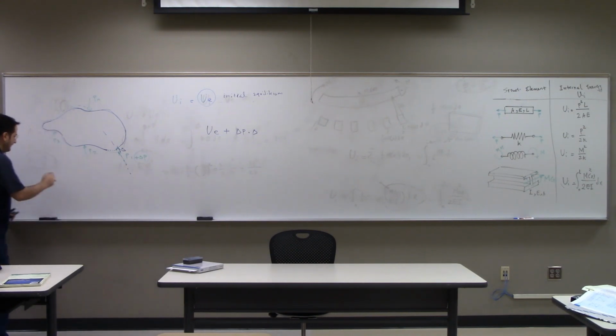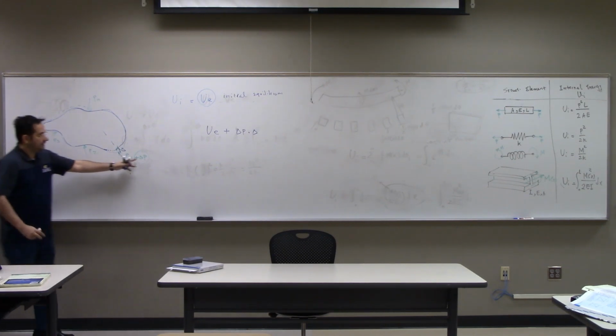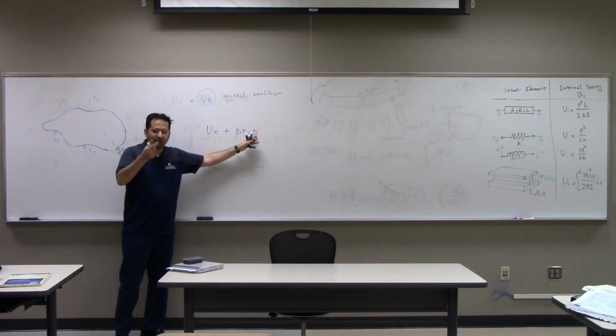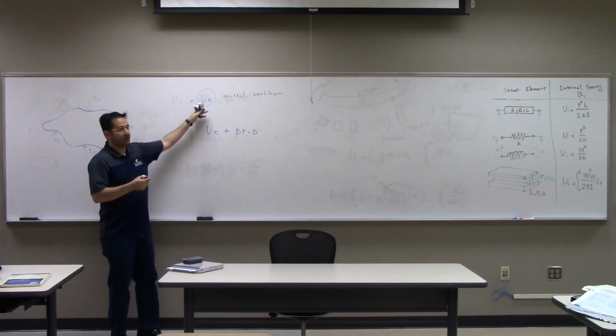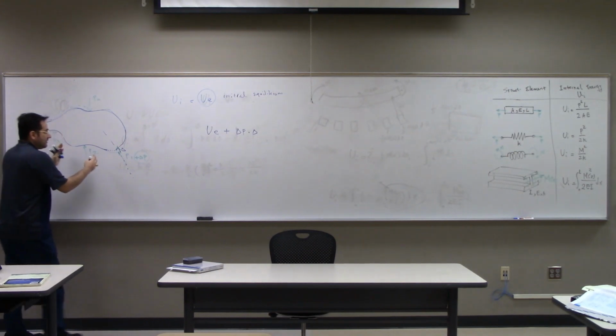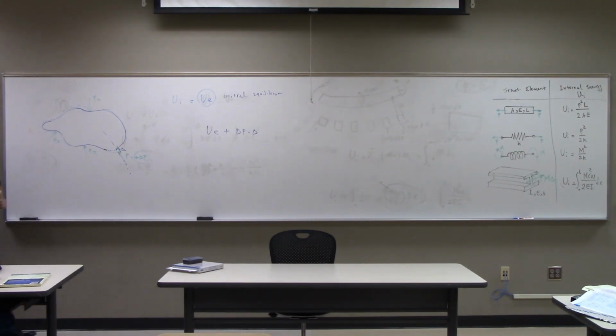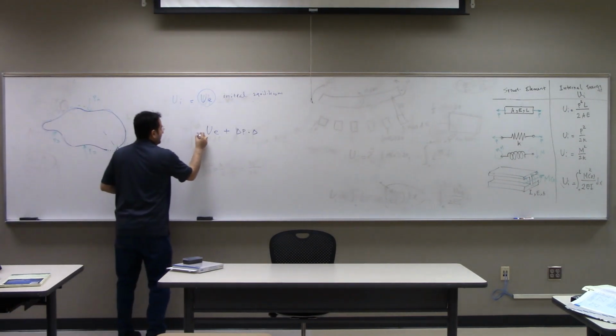You remember if you had final P over the delta, then the integral under this external work was half of P times delta, right? But in this case, because this P is just infinitesimal, then just delta P times delta is the external additional work that I needed to add in order to transfer this system to a new equilibrium, where I have some delta deflection.